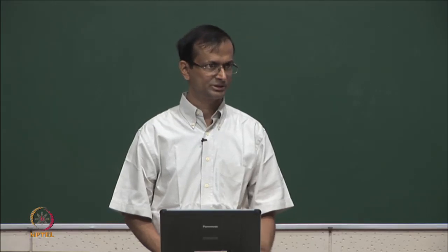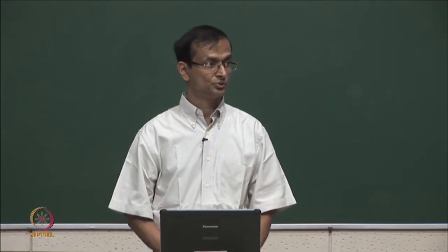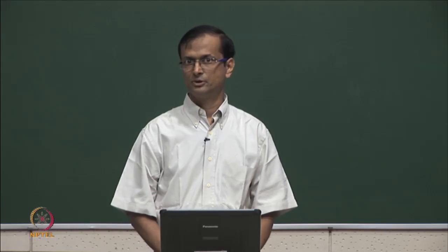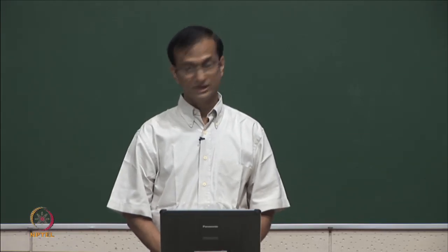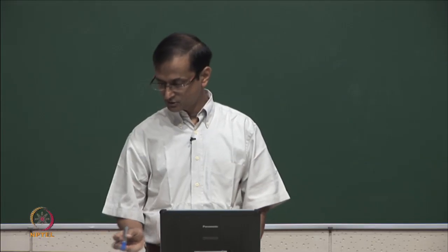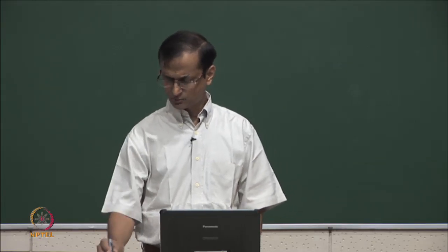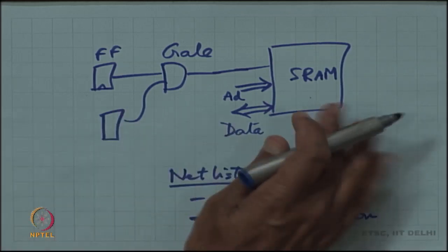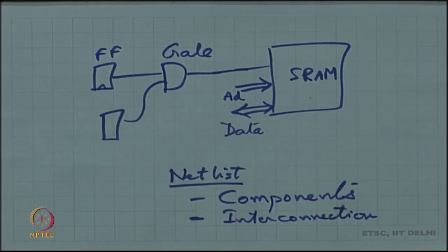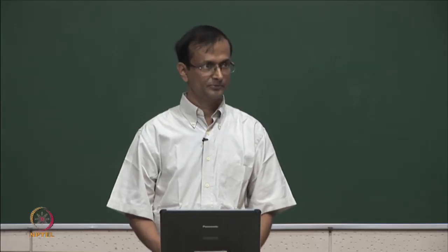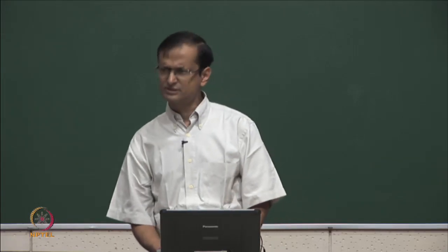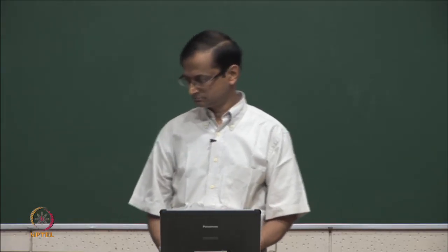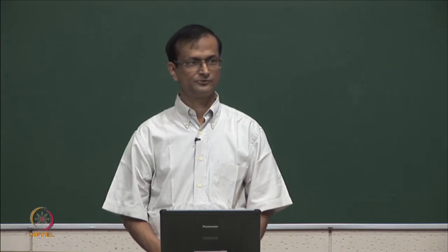These hardware description languages allow us to specify this kind of behavior, which is in addition to saying what the components are doing. Remember, as I drew this netlist here, I did not say anything about what is happening in this component. We did talk about the memory, but separately, that was not obvious in the diagram. What each block is doing was not obvious, at least not yet. So, a netlist is a description of structure only. And that structure is actually very simply specified. It is specified by some inclusion of components.